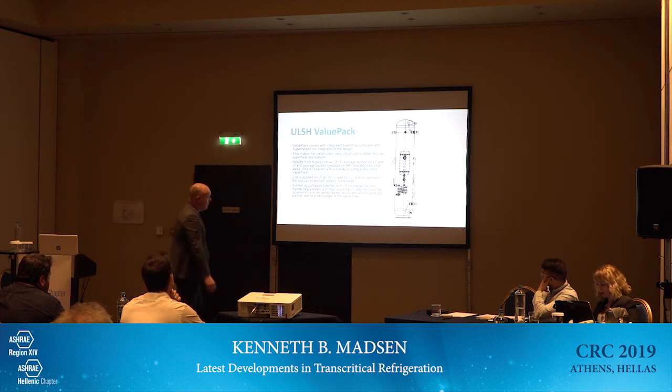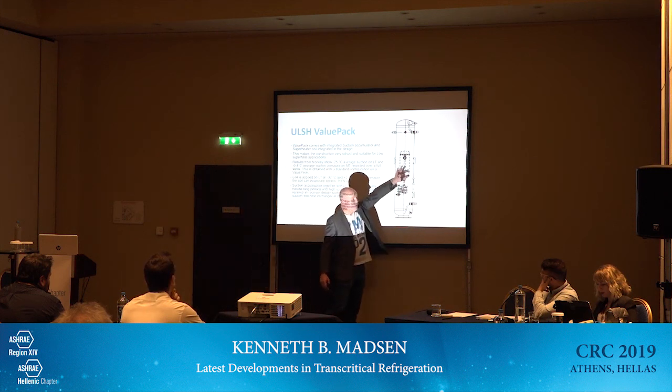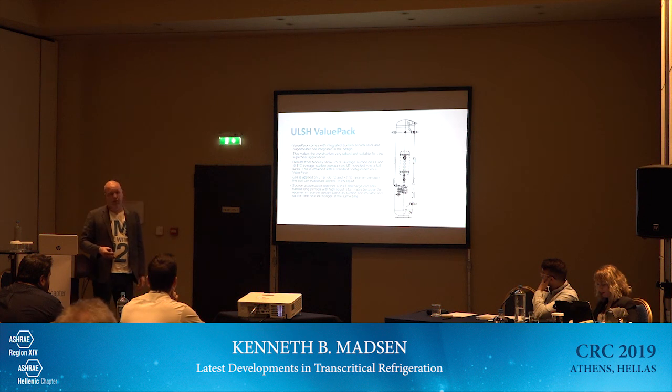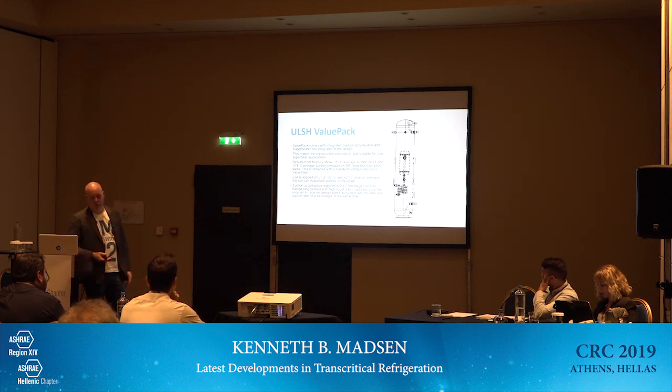And on the medium temperature, we have a vessel inside the receiver. So the gas and liquid coming home to the rack from the evaporators, the liquid part is basically captured in the vessel. And since the vessel is hanging in CO2 that is, let's say, 10 Kelvin warmer, the liquid that is left is basically being evaporated. So on smaller systems, we are not using the injector, and we are using this simple solution to evaporate the liquid. This has actually proven quite useful.